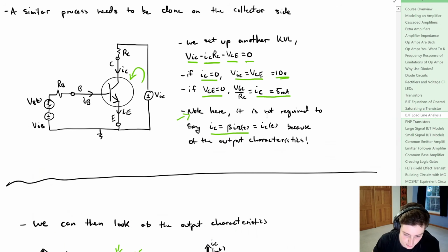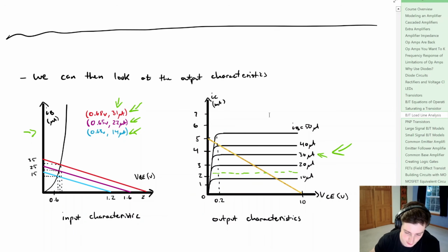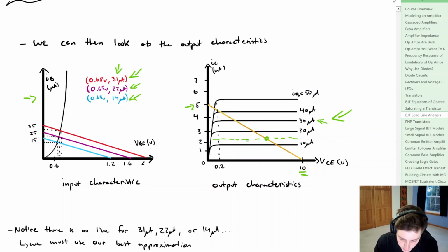So from the values we found up here for our conditions, that's where we're going to connect our load line. So we have 10 volts right here and 5 milliamps right here. So we draw that line that connects those 2 points. So if we note where that intersection is, it would be between these 2 points, so we know that we would hover on this line.